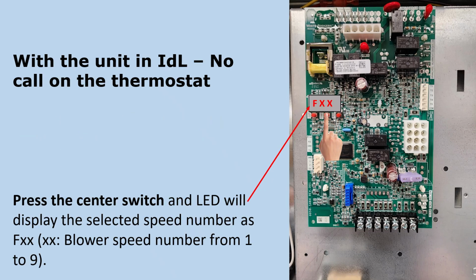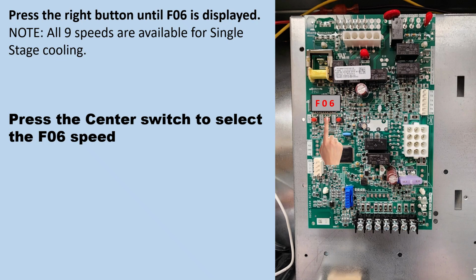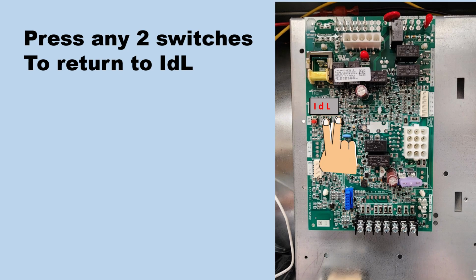Press the center switch and the LED will display the selected speed number as FXX, and the XX is going to be for blower speed numbers from 1 to 9, and when you select them it will be 01, 02. I think you get it. Press the right button until F06 is displayed. Note, all 9 speeds are available for single stage cooling. Press the center switch to select the F06 speed. Press any two switches to return to idle.